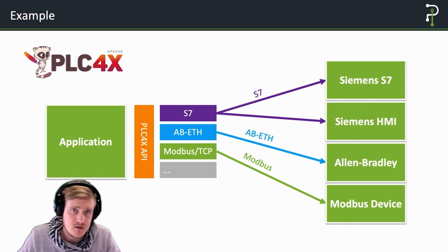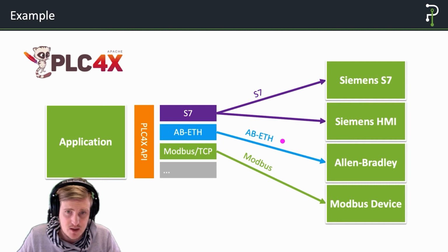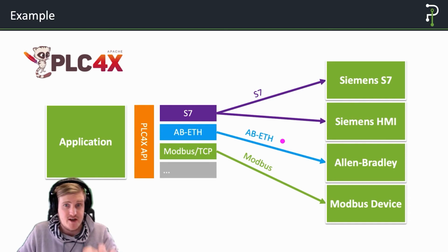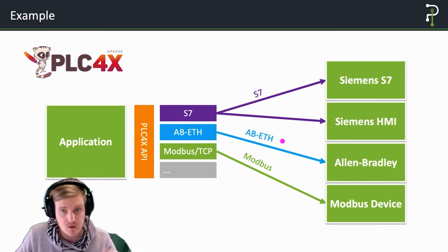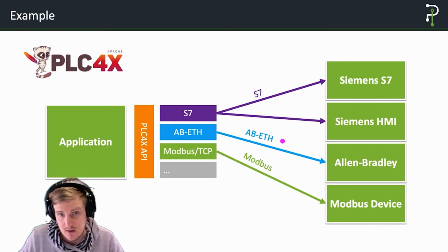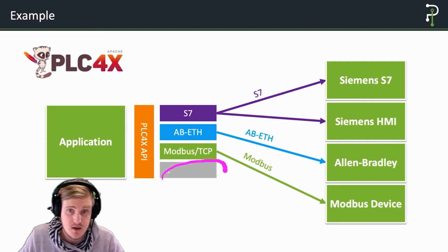With most of those wire protocols that you use directly via PLC4X, it's just bytes that you get over the wire. Some do not even store a type for the information. That's basically like grabbing into a byte array and fetching something out of it. And you have to know what was stored there and with what encoding it was stored there to deserialize it reasonably, which is tough work on the configuration side of things. So this is something that OPC solves way, way easier. And therefore there's also a perfect reason to incorporate OPC UA in such a setup, because when you have it accessible, it's usually nicer.